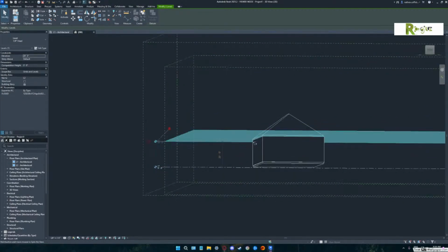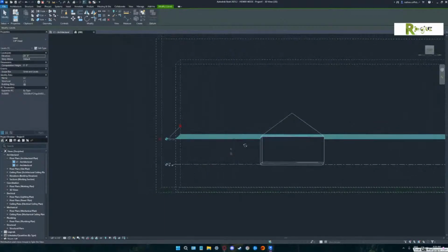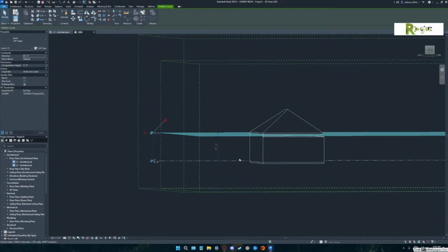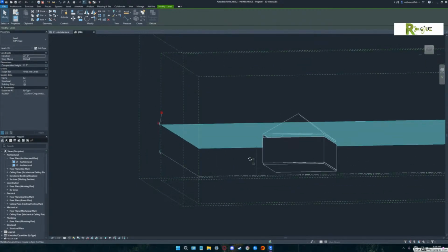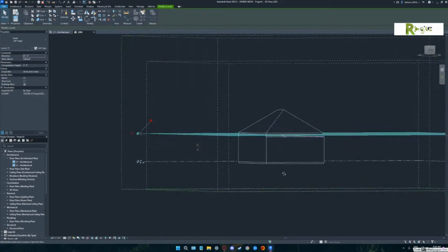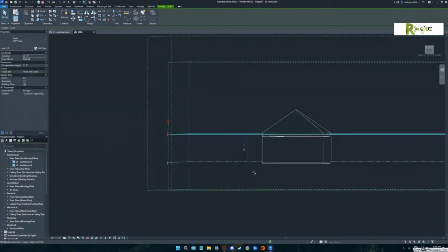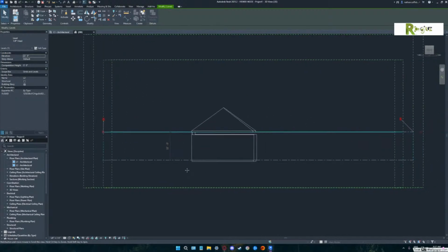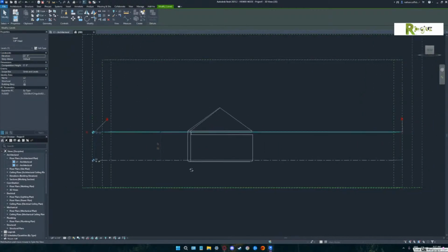Do you see there's also a 20-foot dimension? You could click on that as well. Right here? Yep. That's called a temporary dimension. So if you made that 22 or 30, yep. And you see how 3 of the walls aren't doing their job? That's because when it attached them, they just sort of missed the wall.